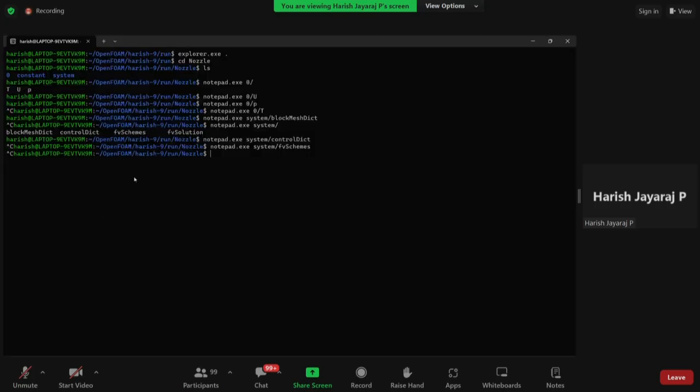Okay, so we don't have to look at the FE solution, there isn't much, but if you want to explore, you can do it. Now, again, we are in the same directory. We did not change any directory at all. We are in the 0, constant, and system. So before we see the constant, first we will run our blockMesh.